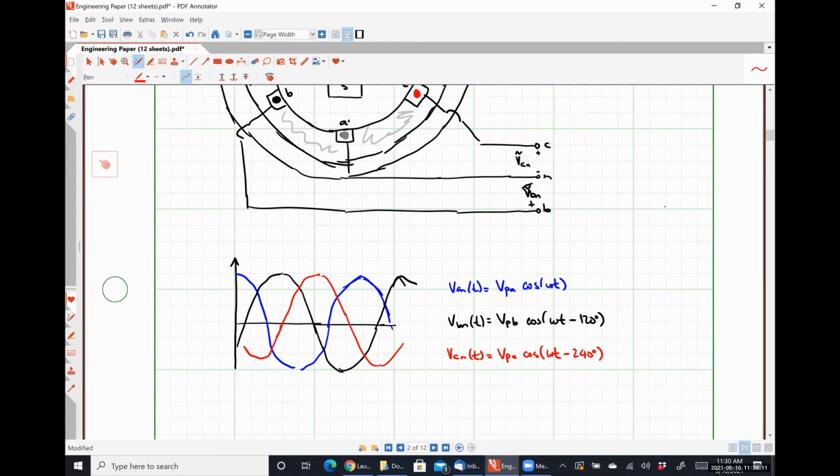That happens 99.999% of the time. The only way to get an unbalanced source is to physically screw it up. So that's never going to be the issue effectively. It's always going to be something on the load side that's going to set up all your imbalances. Okay, so I just wanted to be clear about that. So the margin of error for the robots is very, very small. We're talking about you might be off by tens of millivolts when you're outputting 400 volts RMS. So it's very, very small.